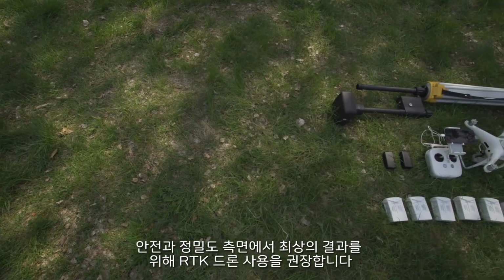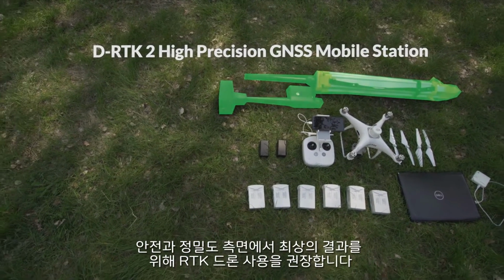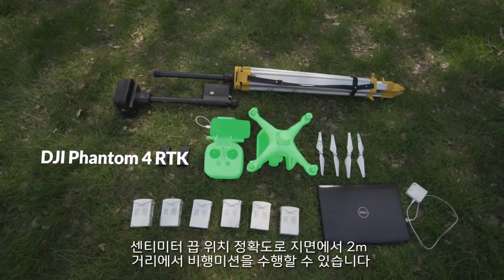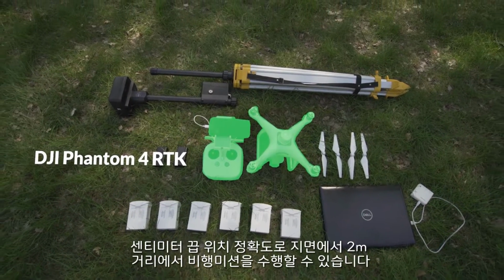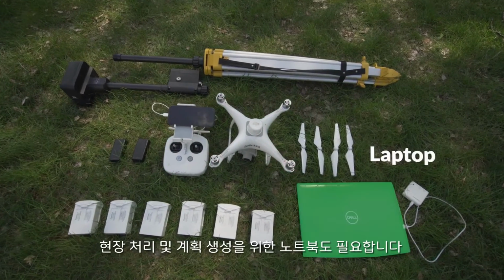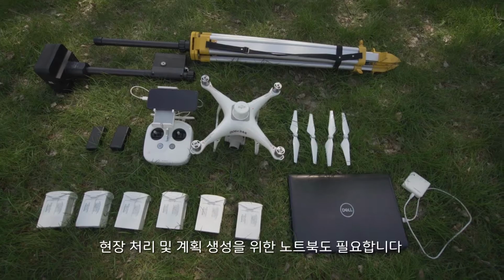For best experience in terms of safety and precision, we recommend using RTK drones. They allow performing flights as close as a distance of 2 meters from the surface with centimeter accuracy positioning. You will also need a laptop for on-site processing and plan computation.